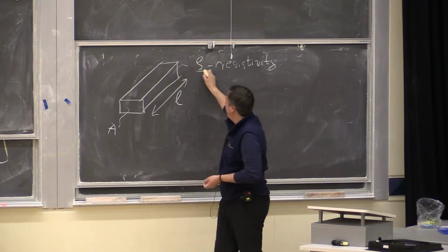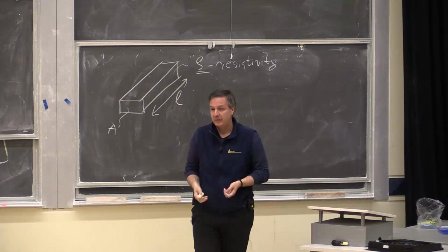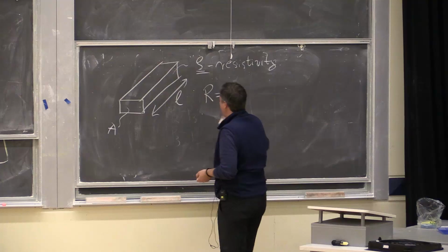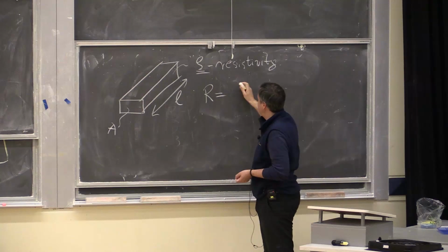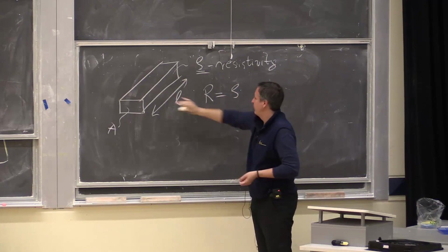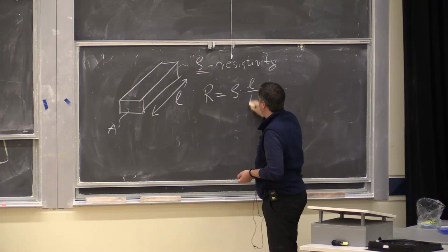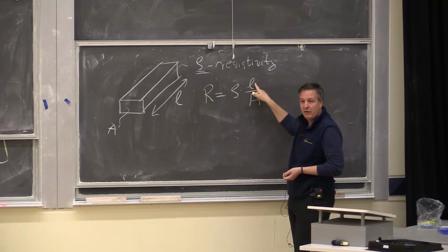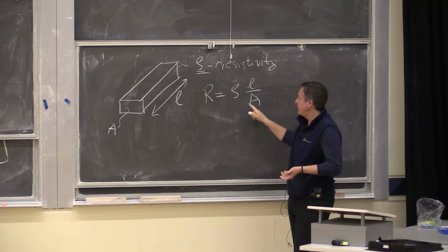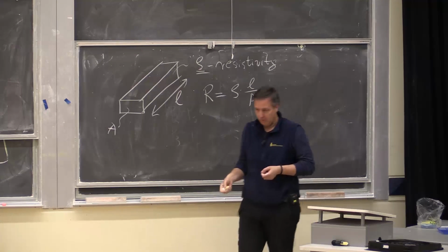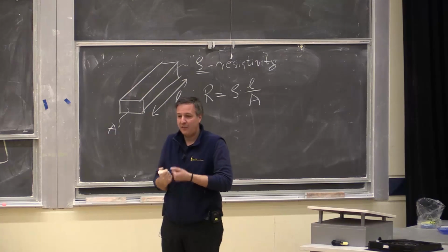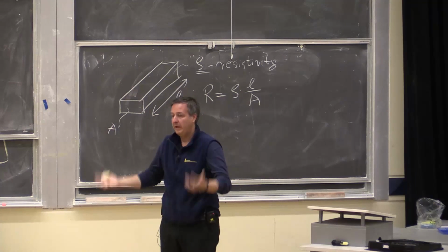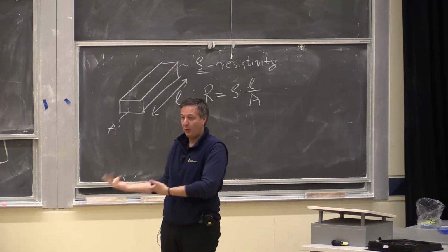that would mean I can characterize that with some constant, which is called resistivity. And I will be able to also characterize this constant for a given physical wire by basically this relationship. This is the resistivity of the wire, the length of the wire, and the cross-section of the wire. And what this means is the longer the wire is, statistically, the more likely for my electron or piece of charge to hit some atom in that wire. So, you lose the energy.